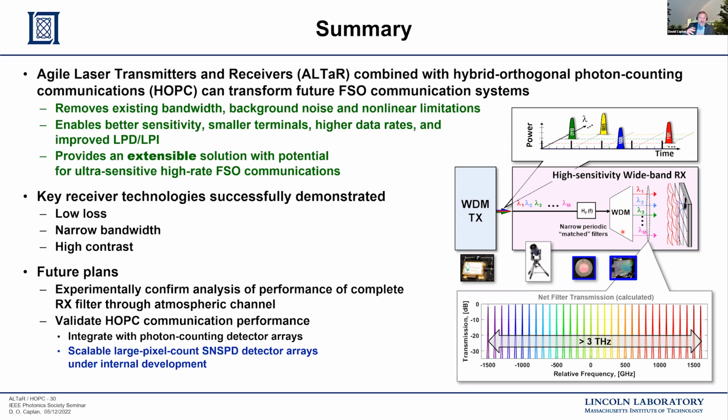And so now you're talking about something that's passive, but really big and hard to make. And so this design of an IIR Fabry-Pérot etalon combined with an FIR type, finite impulse response, diffraction grating design is a nice combination that allows for the entire implementation to be done with a small size, weight, and power configuration. But the Viper is an interesting idea.